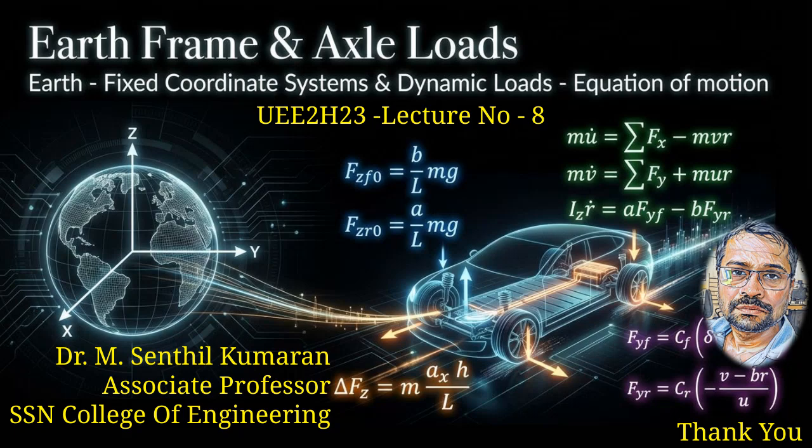Today, we learned that static axle loads set the baseline weight carried by the front and rear tires when the vehicle is at rest. This baseline depends only on vehicle mass, wheelbase, and CG location. We then saw how dynamic load transfer occurs during acceleration and braking. Longitudinal acceleration creates an inertial force at the CG height, which shifts load between axles by the amount delta equal to m times a times h divided by L.